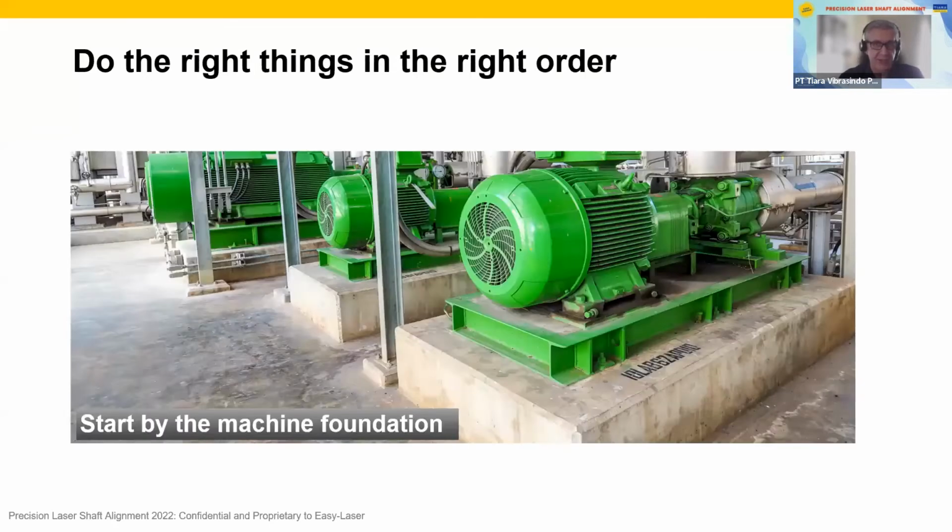So the installation of rotating equipment must follow a certain order. These procedures are designed to always start from the machine base. The foundations are the cornerstone of the entire installation of the machine. They are designed to hold the rotating machine and to transfer and dissipate stresses and dynamic forces produced by pulsation and the machine process itself.